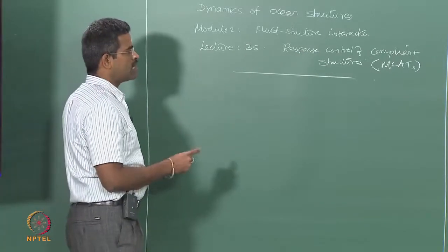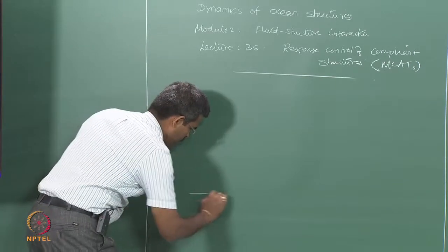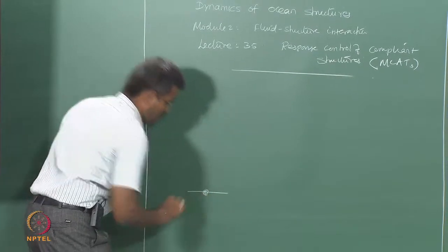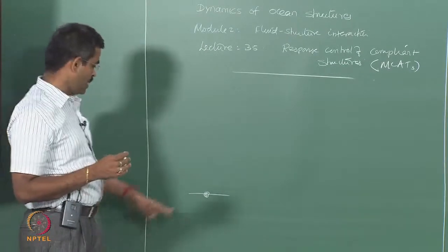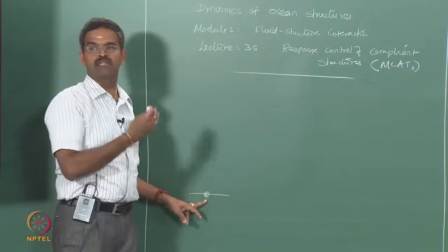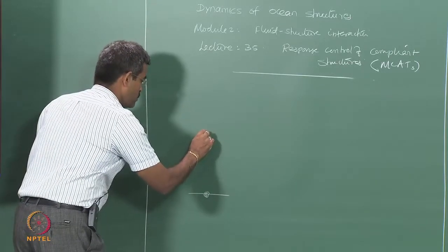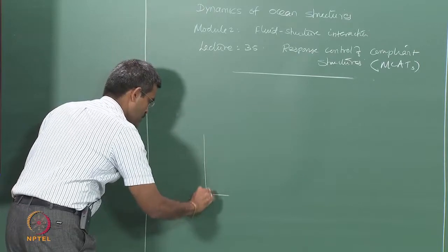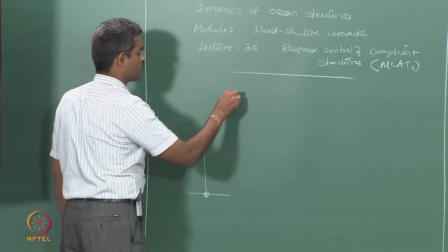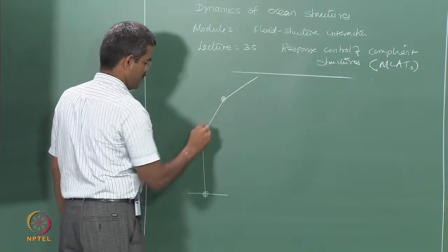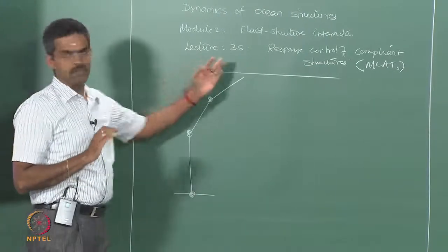So now to understand multi-hinge, we already said that I have a hinge at the bottom which can be identified as a universal joint with a spring, because it has a rotational stiffness m theta. If it is a single tower, it is AT, if it is multi-tower, then it is hinged, and so on. These are the points where the hinges are located. So it is such an inverted pendulum actually.